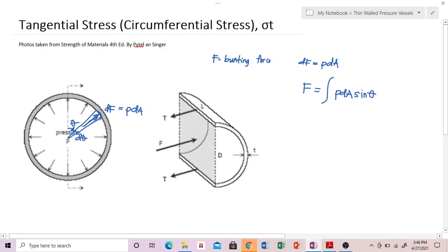Okay, next. So, F is equal to, our limit is from 0 to 180 degrees. Now, F will be equal to integral of P. Ang dA natin is, what is dA? Ito yung differential area natin, yung element, that is length of an arc multiplied by L. Diba?